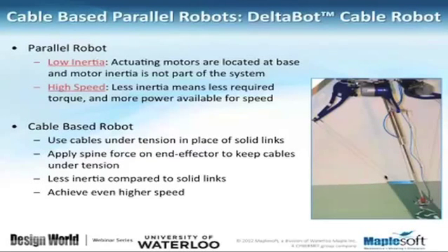Now, one benefit of this, as I said, is reducing the inertia. The other advantage is reducing the overall cost of this robot, because instead of using carbon fiber, we use cables, which are much, much cheaper. And the second one is to eliminate the load capacity limitation that we have in conventional parallel robots. With this robot, we can run it at high speed with low mass, and also at high capacity, 20 kilograms at low speed, without any problem.